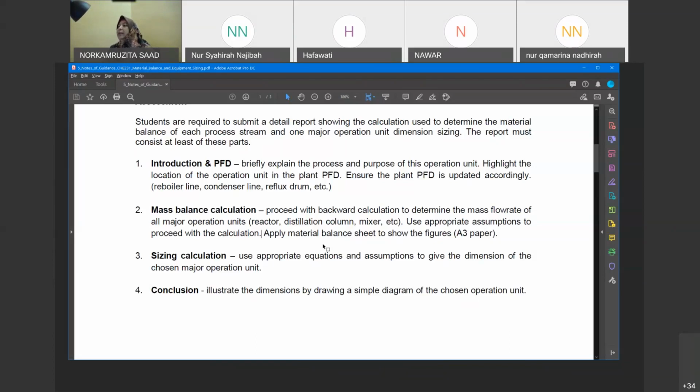You use that assumption, and you may also assume that you have 25 trays, for example. But when you assume 25 trays, you don't get the 99% purity you want for your product, let's say 99% of A from B plus C. So you have to adjust. If I want 99%, I can't use the trays that are already there. So I should add more trays.